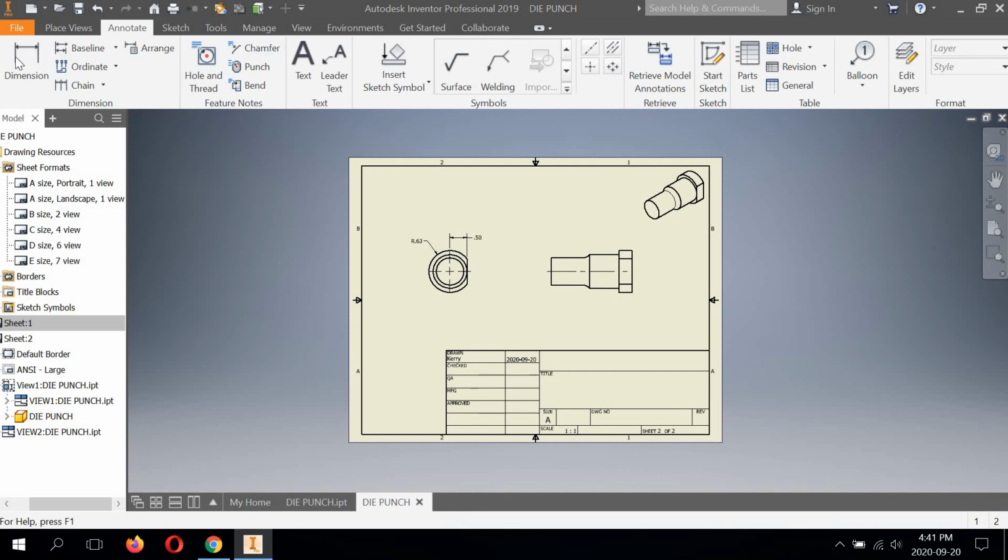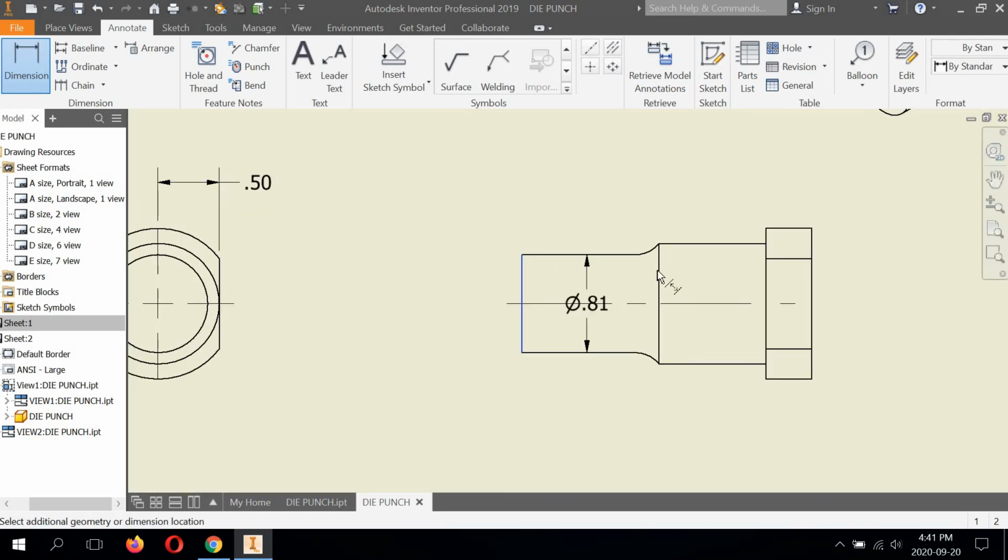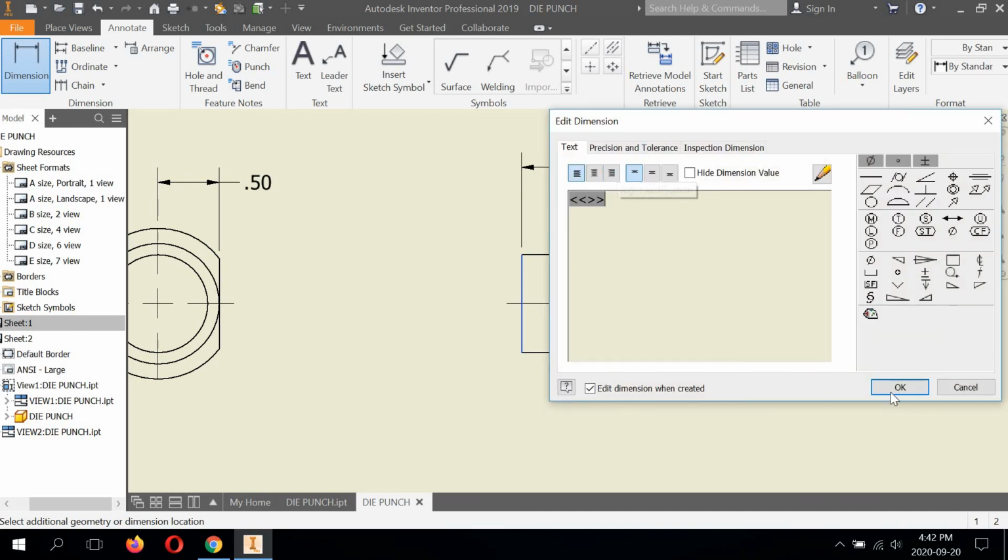And we're going to, again, start with a general dimension. And we're going to dimension from this line to this line. And again, see what happens. When I bring the dimension up, it basically gives you a little break with all these dots. That's giving you an indication that this is where you should snap it so it's not too far away. We're actually going to go one more up. And I'll explain why that is later. So hit OK.